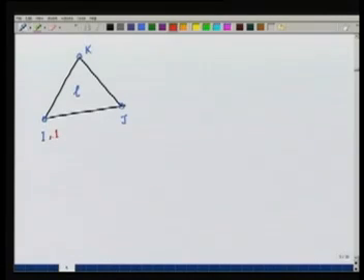So what do we do when we go to the element convention? Then this I will correspond to 1, this J will correspond to 2, and this K will correspond to 3. So in the element, I am giving a new naming convention. This is my node 1, 2 and 3. Okay. So corresponding to this node, I had phi I globally. In the element, I'll call it N1 of the element. Here I had phi j globally. Here I'll call it N2 of element L. And here I had phi k globally, which is the same as N3 of the element L.